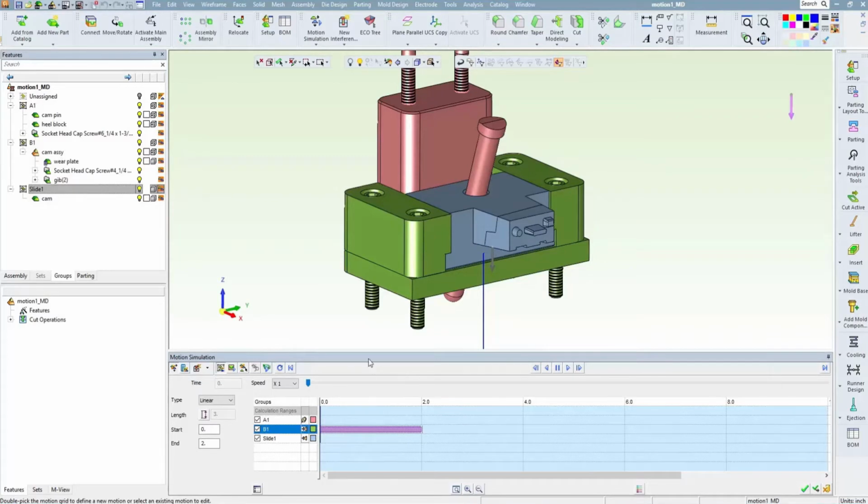The second aspect of the force definition is the concept of time. The time grid allows other motions to be defined in a certain order. How long one motion lasts doesn't really matter, except that by default the system is set to run calculation every 1/10 of a second. So by making the motion over a larger period of time, you add more calculation steps and generally refine the accuracy of the analysis.